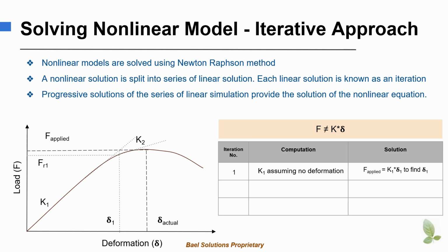Note that in the nonlinear models, stiffness during the deformed state and the undeformed state are different. Therefore, reaction force does not match the applied load. This represents the error in the solution, known as a residual.